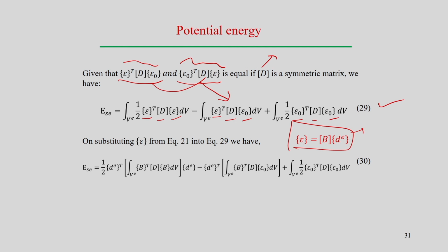So, basically the stress components are replaced in terms of the strain. Now, all the terms in this energy are associated only with the strain components. Now, we will look into the relation between the strain and displacement. If we look into that relation, then it will be possible to replace the strain components in terms of the displacement.